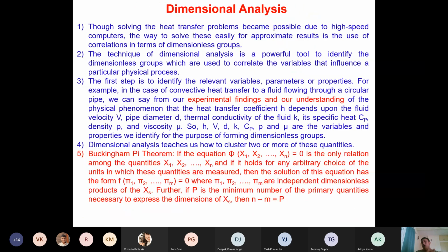Okay. So now as we were discussing, our analysis is going to get simplified immensely if we use the correlations for the heat transfer coefficient, because that is going to account for the velocity distribution. It is going to account for the effect of the change in the properties, everything, correct? And because of that, I just have to write Newton's law of cooling and find out the rate of heat transfer. I don't have to do anything more than that, isn't it? That is what it is.